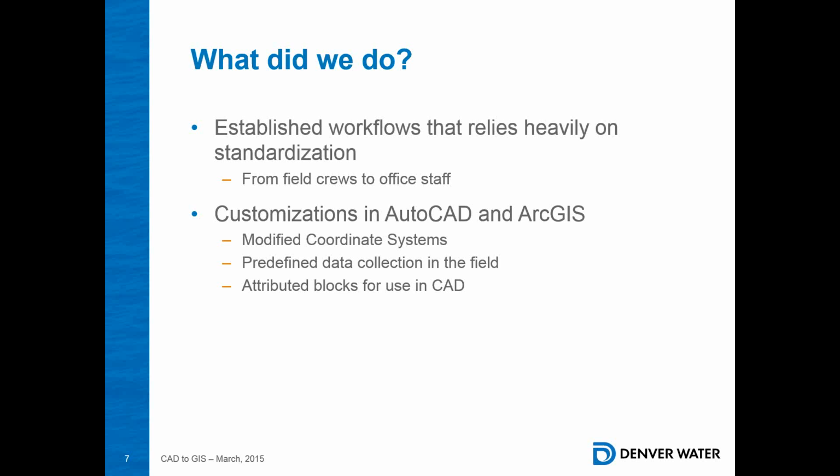And think about that workflow, because rather than have the data collected twice or the data collected once and shipped off to two different groups and heaven knows what happens to it, we've got a straight line workflow here that Denver Water built. And this is what's really clever: while we can export out of a data collector as a shapefile and bring that into CAD, I can't use it if I just do some kind of overlay, like a shape overlay, like an FDO connection, right? Yeah, we can't ship that to our asset recording group because they can't post it to ArcGIS.